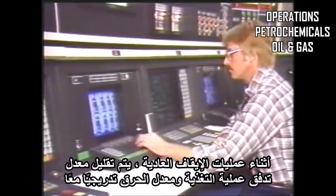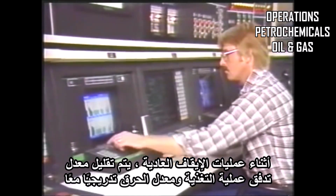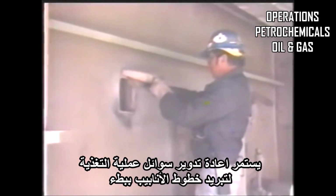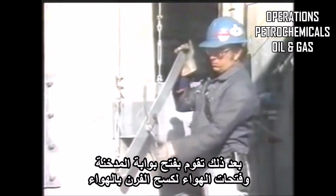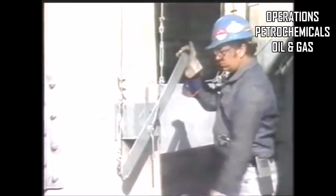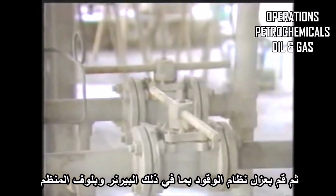During normal shutdown operations, the process flow rate and firing rate are gradually reduced together. When minimum firing has been reached, you shut off fires and open the peep doors. Process circulation is continued to cool down the tube slowly. Next, you open the stack damper and air registers to purge the furnace. Then block the fuel systems, including the burner and regulator valves.